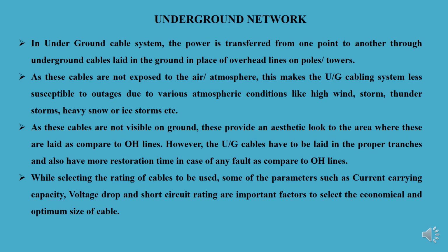While selecting the rating of the cables to be used, parameters such as current carrying capacity, voltage drop, and short circuit rating are important factors to select the economical and optimum size of cable. So which type of cable do we have to use? For the selection, we consider current carrying capacity, how much current you have to supply, whether 230 volts, 11 kilovolts, or 33 kilovolts. According to that we decide the quality or which type of cable is suitable for that particular location.